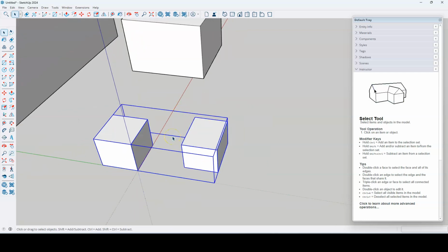Now, if you've noticed that you have created your two cubes within the same group, and you didn't mean to do that, no problem. To get out of a group, or dissipate a group, I don't really know what word to use, we call it explode in SketchUp. So when you're outside of the group, not within editing mode, you right click the group and hit explode. And that's gonna put it back to its individual geometry.